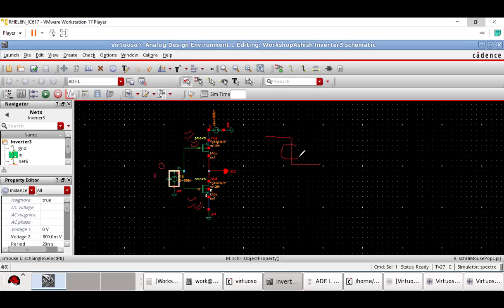But when you do this, there is one situation where there comes a point when NMOS and PMOS are both on. When NMOS and PMOS are both on, then what will happen? Everything that starts from here will get grounded. Right? Let me show you one example of this.